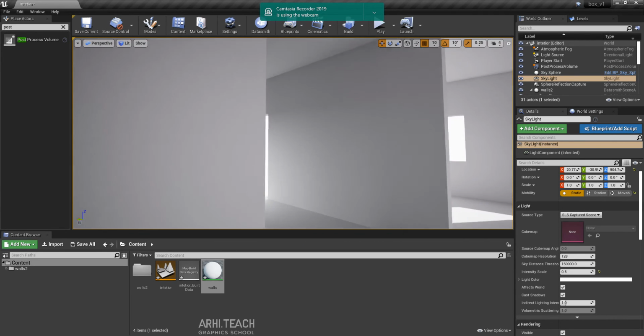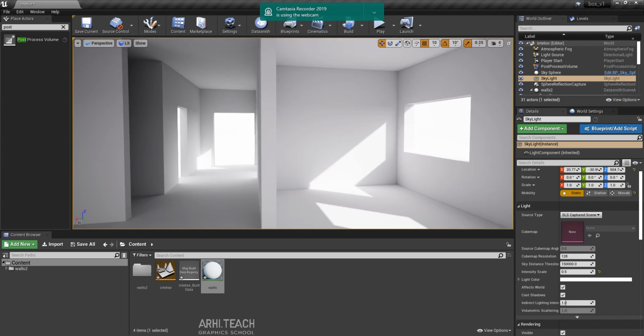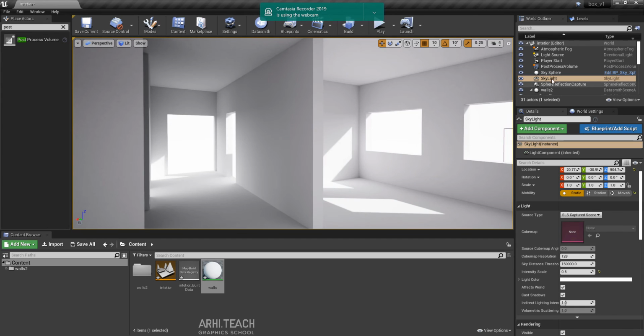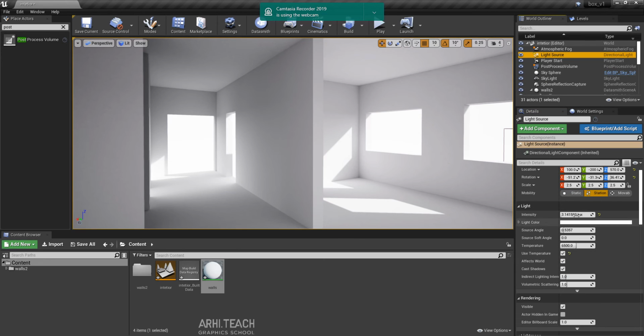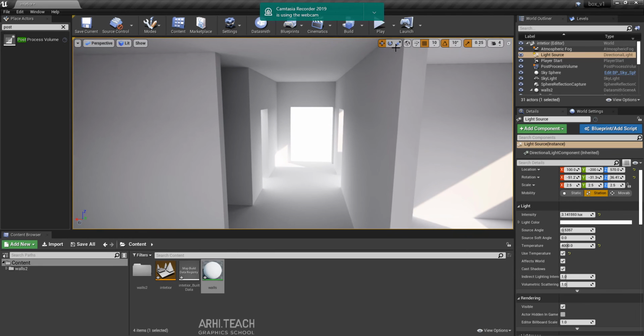You see, photons, noise, such messes here. We'll fix it now. So we select skylight. Here we put 0.5. Okay, now our sun directional light will make it warmer. So we set 4000 here. So a shade of sun like this we've got.